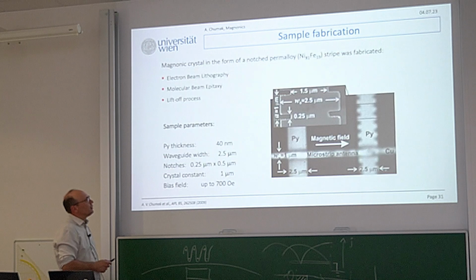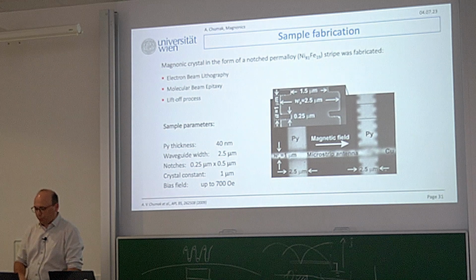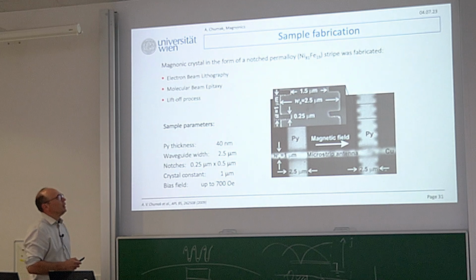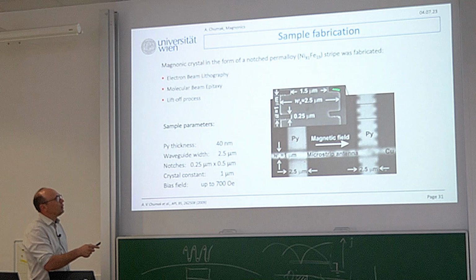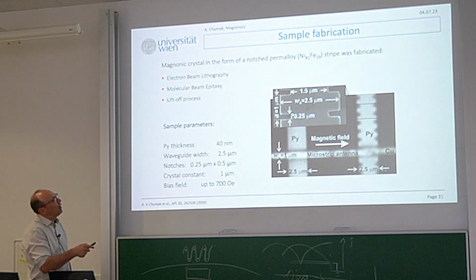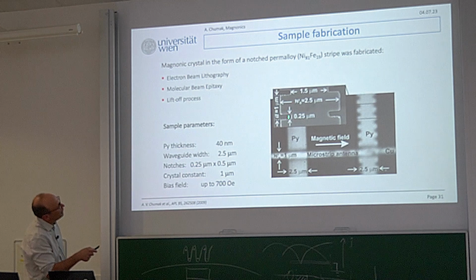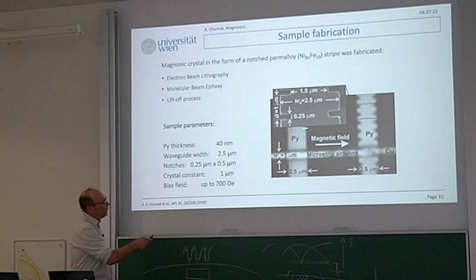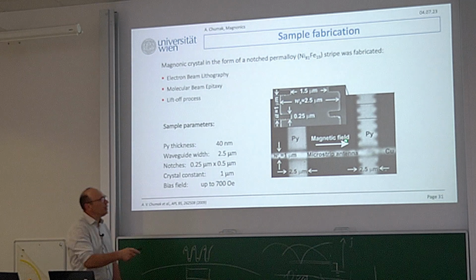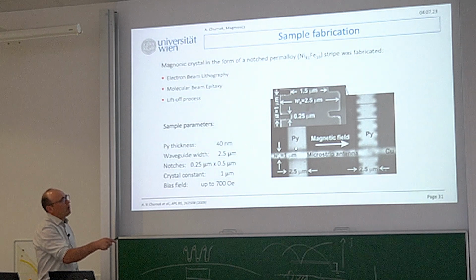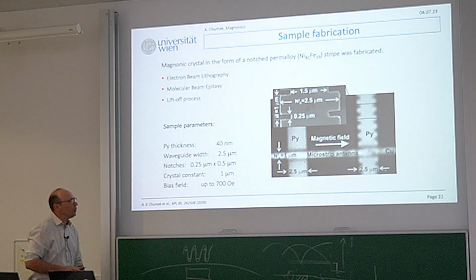So it's all good. For us, of course, experimentally, the question was if it's possible to bring it to the microwaves to experiment. And this is our first experiment in Kaiserslautern. We used permalloy, 2.5 micron wide, 1 micron periodicity, and these notches are like 25 micron large and, I don't know, something like half micron in depth. And then we used a microstrip antenna, simply a strip line antenna, to excite spin waves in the reference permalloy waveguide without notches and the waveguide with the notches.